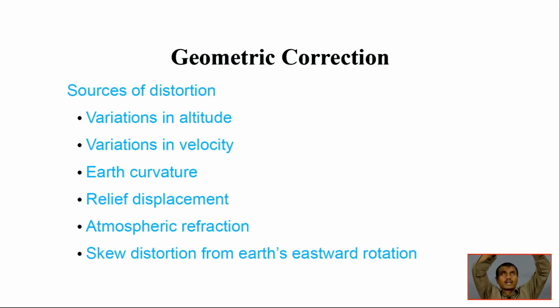And when you are collecting the image from the satellite, due to these variations in height in the surface, in the structure, there would be some amount of relief displacement error in the image, so we have to apply some amount of relief correction, because when the satellite is collecting, it is a flat surface to the satellite, but actually we know there are height differences. So, we have to apply some correction, that is relief displacement. It is very much relevant when we are going to reconstruct in 3D the whole dump structure. So, we have to consider those correction factors as well.